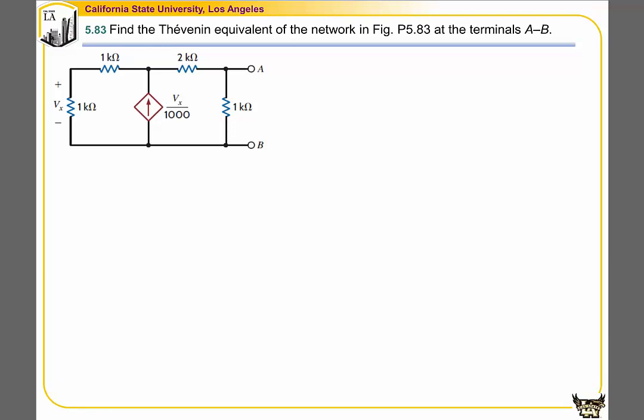It implies that if we use the traditional method by finding the voltage between node A and B, we'll find 0. And if we calculate for the current, we will also get 0. This makes it impossible to determine the Thevenin equivalent resistance. This also belongs to case 2 that we talked about in the class.